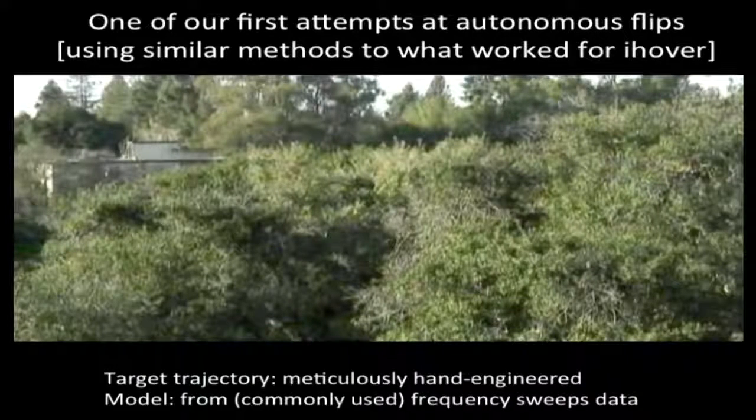But definitely the autonomous controller completely failed. Pushed the controls too hard. Why would that happen? The reason that happens is because the controller was designed based on a simulator. The simulator resulted in a sequence of linear controllers that are pretty good in the simulator, but the real dynamics don't match up. So it starts deviating from the trajectory. Then, after it deviates a bit, the dynamics start deviating even more from what the simulator had. The linear controller is even more wrong, and this keeps going on and on. You destabilize, it goes out of control.